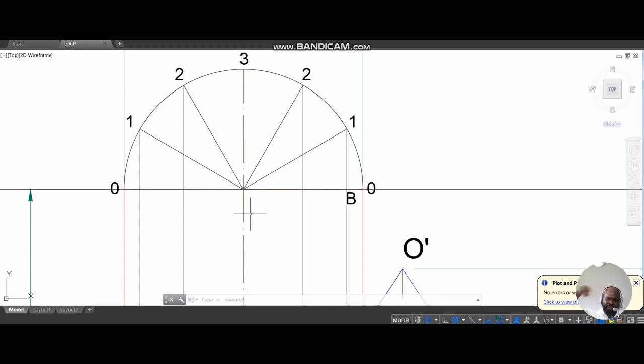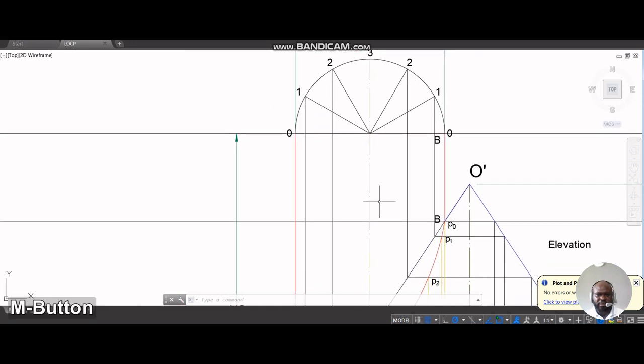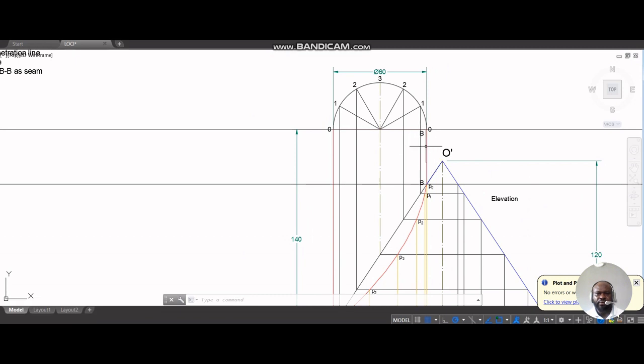Since the cylinder is a circle, the other half of the cylinder is also divided into 6, which means that, as with the principle of the development of a cylinder, if we open up the cylinder, we are supposed to divide it into 12 equal parts.